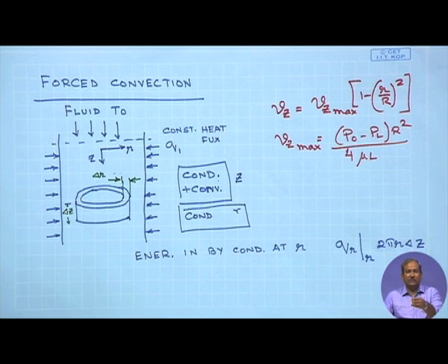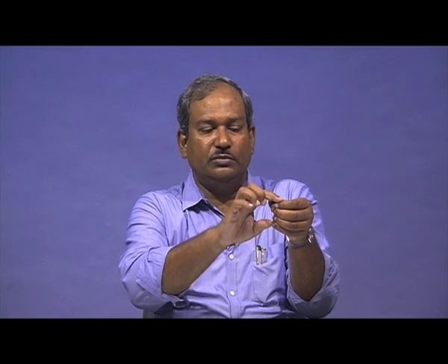When you have the annular area and you are talking about flow of heat in this direction, the area that it faces is 2 pi r times delta z, where delta z is the length of the shell and r is the inner radius. This gives the area through which the conductive heat in the r direction is entering the imagined shell.